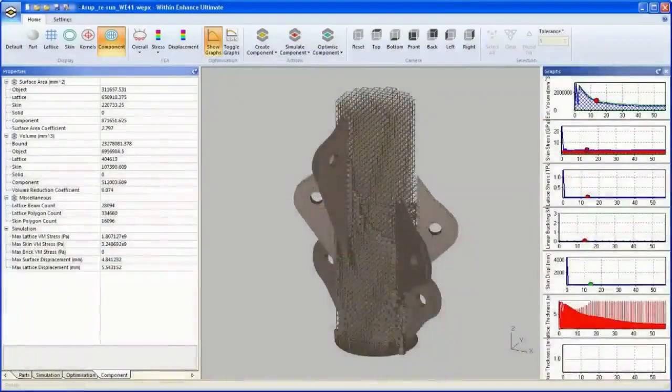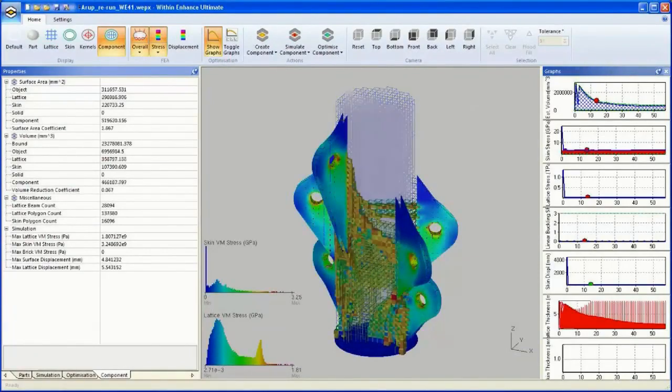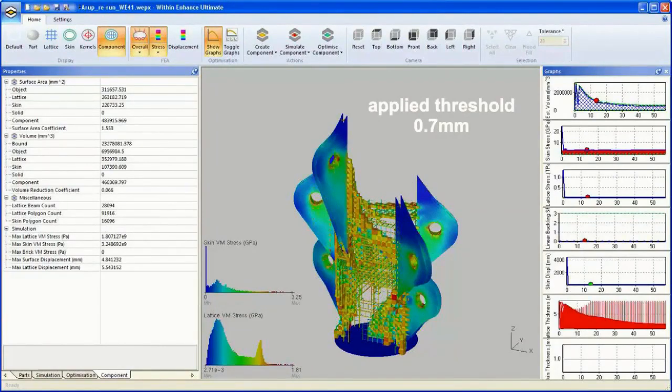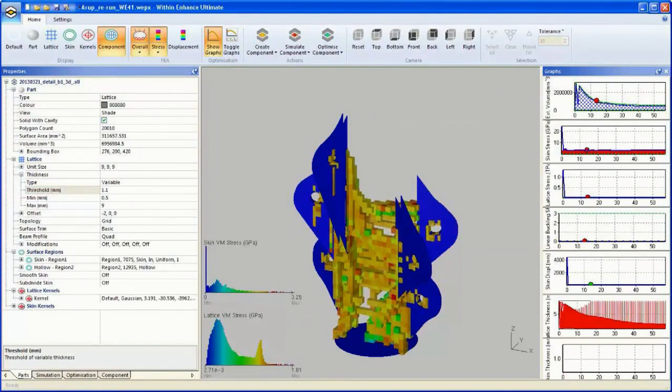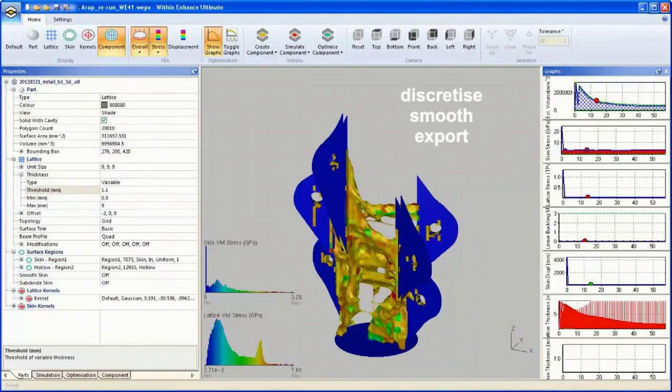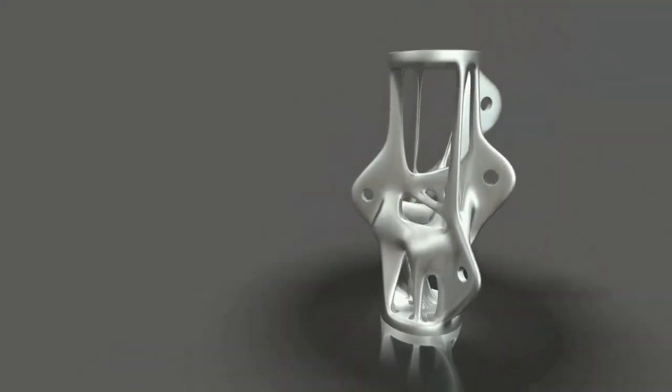So the first thing that they looked at was how much weight they can reduce from their component using really the shape optimization that we were talking about. So it's applying the loads and constraints, finding out where it needs the material and where it wouldn't, and then resulting with the ultimate component for that process. So then you can see again, this is something that's completely unique from what they had at the beginning, and it's also something that now they can make every single one of these very unique.